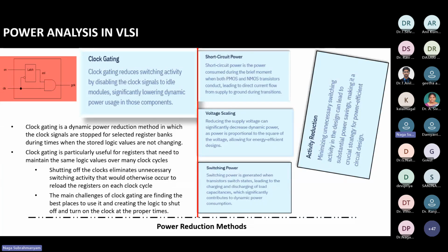This is point number one. Number two, as soon as the system wakes up, it has to be in a known state. As soon as we remove the reset, the system has to be in a known state. These two are the fundamental requirements for any digital design, and also for the verification engineer. The verification engineer will first look at how the clock is coming: is it continuously there or is it dying? First he will cross verify that.